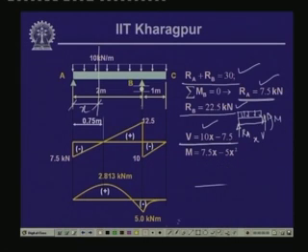and correspondingly if we calculate the value of the bending moment, we have bending moment M, which is acting in an anticlockwise direction. The load gives a moment in an anticlockwise direction if we take the moment with respect to this point. So, M plus 10, this is x and this distance is x by 2, so x square by 2, minus Ra into x, this is equal to 0.